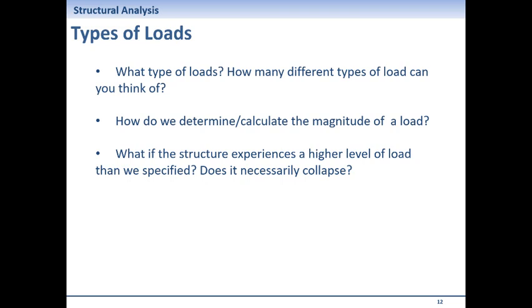So ice, snow, these are also different types of loads that we may not consider in Perth. So we use the standards to determine what types of loads, and also the magnitude.